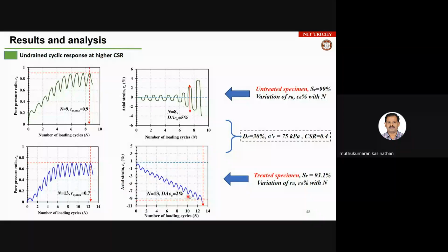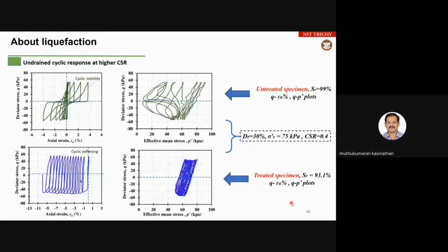And as well, the double amplitude strain, you look at here, does not reach beyond 2%, even with an increasing number of cycles up to 30. So that shows very clearly, increasing relative density is favorable. It is pushing the risk out by some time, but definitely it is still happening. So you need to have an improvement. So that is what we call induced partial saturation.